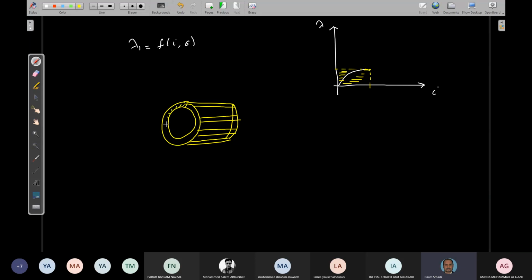So those are the same point. This can be seen as one point, by the way, because all are shorted by a ring. This bar and this bar and this bar and this bar are shorted by a ring from this terminal and this terminal, which means that the rotor here is enclosed. You cannot access the rotor. You cannot connect any circuit to the rotor.